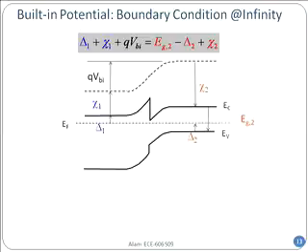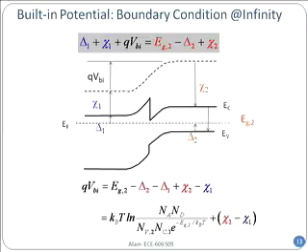So you have to take out minus delta 2, this minus delta 2 business. And you know this delta 1 and delta 2. How do you calculate that? You know the doping, and therefore you can easily calculate how much delta 1 and delta 2 are going to be. So it's very easy actually. You put in the values for delta 1 and delta 2, and remember the two sides do not have the same effective density of state, right? Two different materials, so you'd have different effective density of state. You can see NV2 and NC1 and so on and so forth, EG2, and that's taken care of.